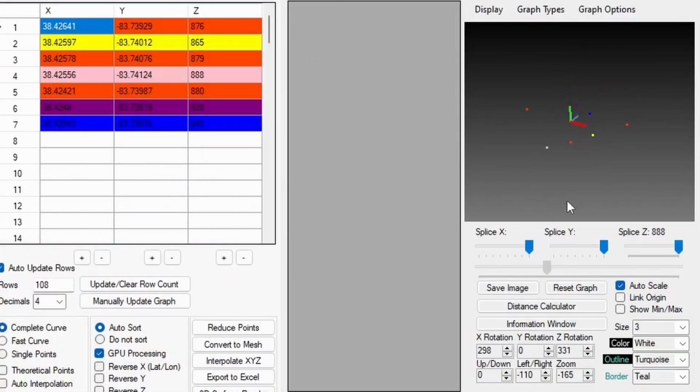Interpolation is the ability to curve data and fill in empty data points without converting the data to mesh first. For instance, say you want to keep your data in an XYZ format, but you still want to generate new points and fill in any empty gaps that there might be in your data. That is called interpolation. If you want to keep your data in an XYZ format, but you still want to fill in the empty data points, just click the Interpolate button.